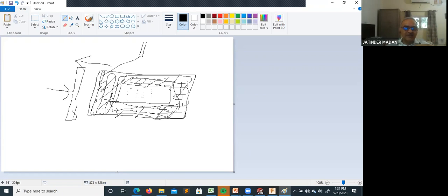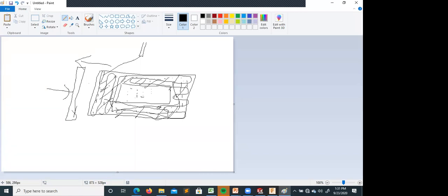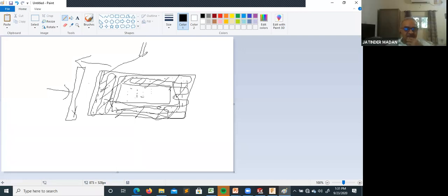This roller will again come and sprinkle powder, the next layer, over it. Now again the laser will come and scan the area where you want to print. The next layer is also printed. So likewise, every time the powder will be sprinkled and the laser will come, your platform will get lower every time. So you are building the part.